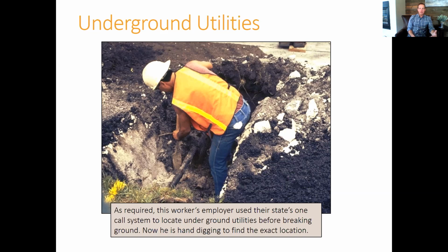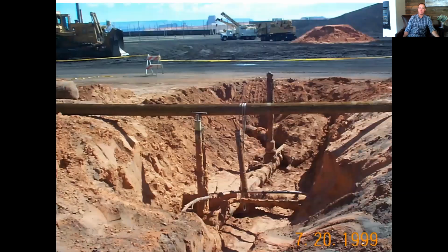But a lot of people get injured and hurt because of hitting things. I'm going to have some videos in that shell that you can watch, where people have actually hit lines, water lines, gas lines, all of the above. So this is a way that you can protect lines once you're in the excavation, by stringing a big pole across and tying those things up. That's an acceptable way to protect those lines once you've found them and they're just hanging in your excavation.